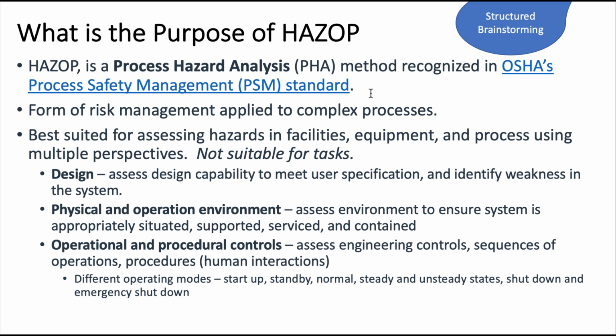You can take a look at the physical environment, and this is where I've used a HAZOP before: to take a look at where the facility is situated within the environment, what happens upstream and downstream, whether the facility is supported by services, and whether the facility is self-contained or not self-contained.